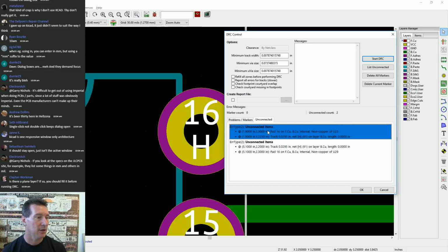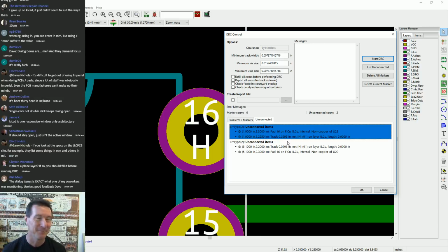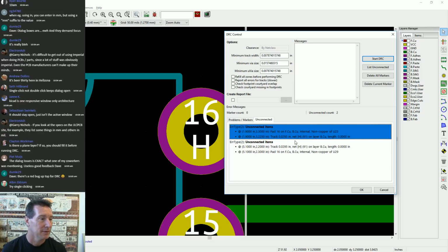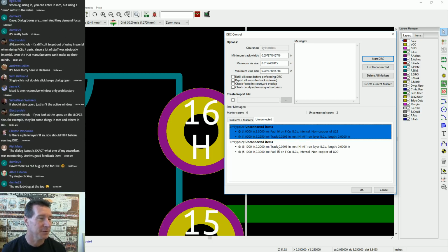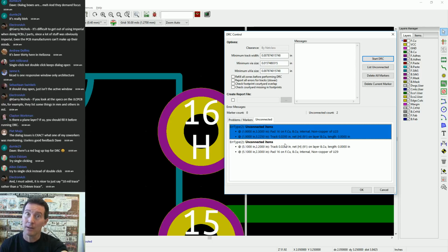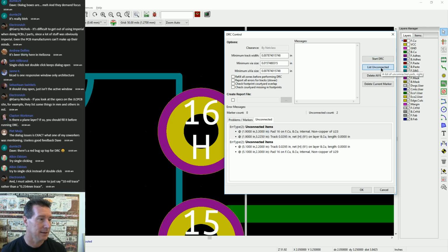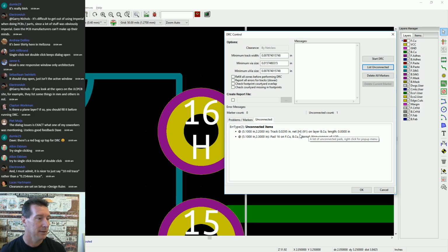And, yeah, so it calls them unconnected items. So, items, like item. It doesn't know what it is. Of course it knows what it is. It's a track, right? It's got an unconnected copper. It knows it's copper, right? So, anyway, unconnected items. But I guess when you're doing DRC, you can do DRC on silkscreen and solder mask layers, so it should say unconnected copper, because it knows it's not an item, it's copper. Unconnected count. Okay, list unconnected. We can redo it.